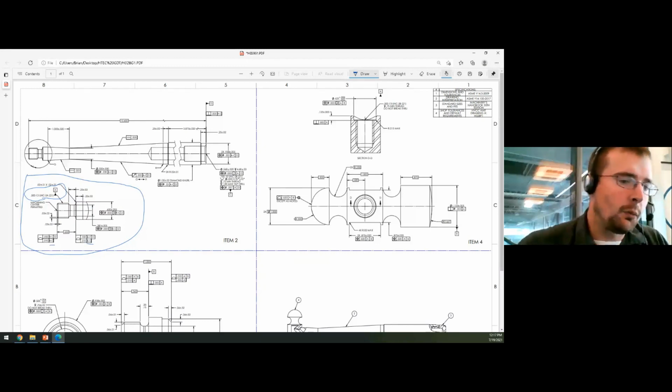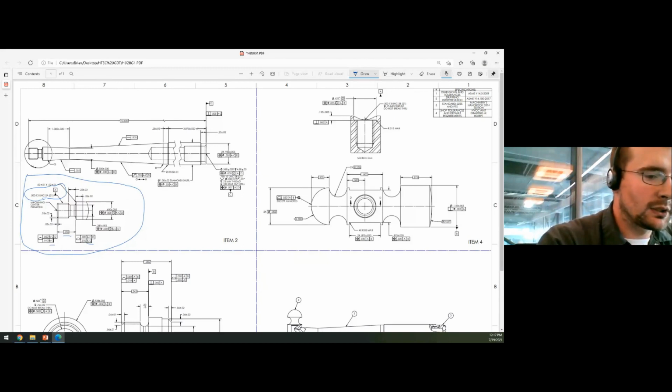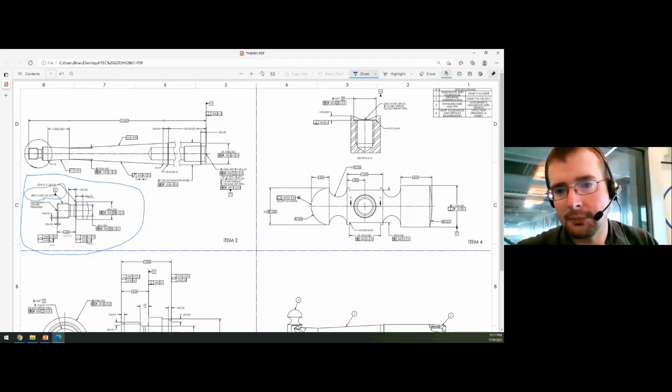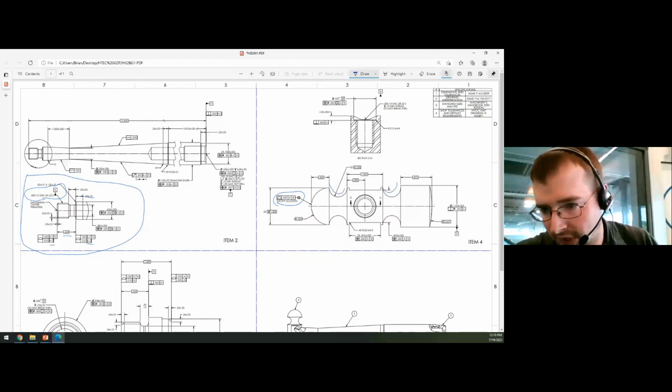Why are some tolerances basic? Why are some not? That really helps, and that's all on purpose. Nothing on this necessarily needs to be as tight as it is. Other options we have here: profile of a surface all around except as noted. We grind form tools for these radii, and we have a form tool that I made for this radii for the students.